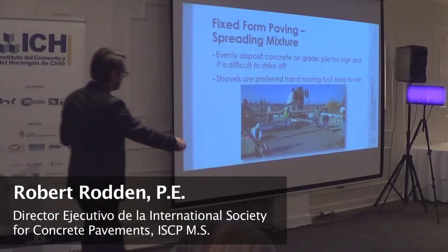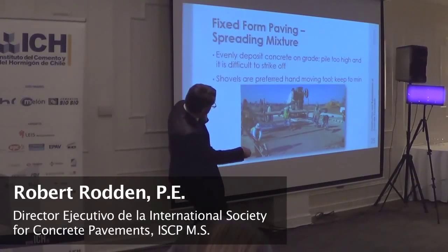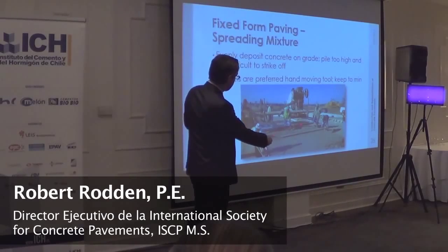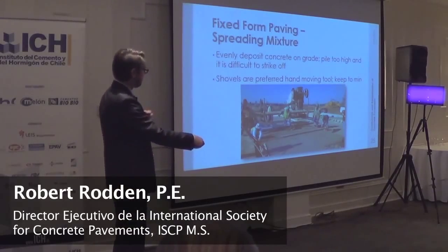But here they're spreading it uniformly. It's being delivered by a ready-mix truck. Here they have a triple tube screed, so those go in different directions. There's still someone spreading it out before they strike it off and finish it past that point.